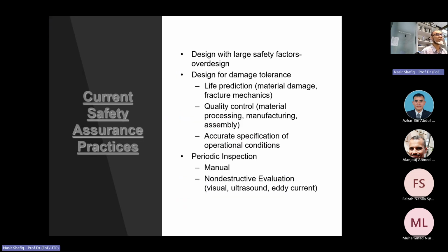Current safety assurance practices: design with large safety factor, over design, design for damage tolerance like life prediction, material damage, fracture, quality control, accurate specification, and periodic inspection, manual non-destructive evaluation, and so on.